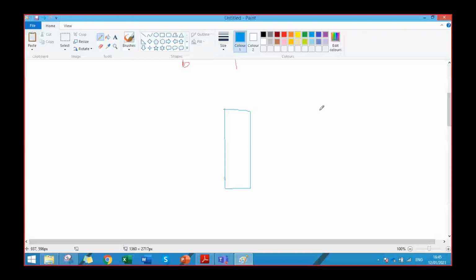So in this case, this is a two-dimensional body and there is flow across it. The area normal of this left surface will be pointing in this direction, and the area normal of the right surface will be pointing in this direction, right? Yes sir. So if we have flow from this side to this side, here the area normal, that is the n vector, is anti-parallel to the velocity vector, right? So v dot n would be negative for inflow. And on the right side, v and n are parallel, so v dot n would be greater than 0. Clear?